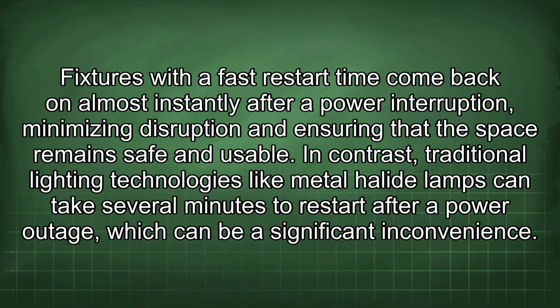Fixtures with a fast restart time come back on almost instantly after a power interruption, minimizing disruption and ensuring that the space remains safe and usable. In contrast, traditional lighting technologies like metal halide lamps can take several minutes to restart after a power outage, which can be a significant inconvenience.